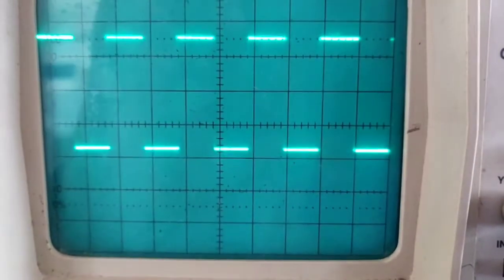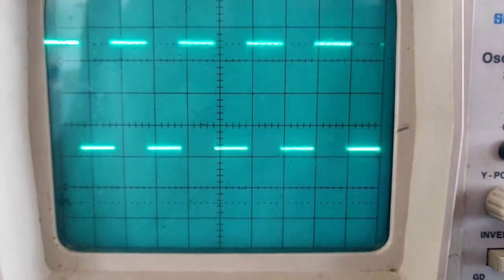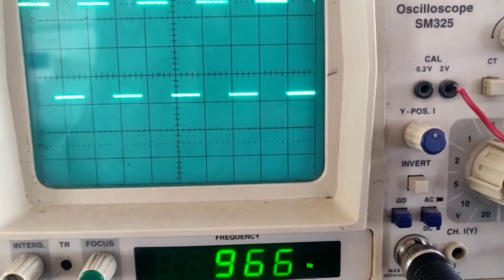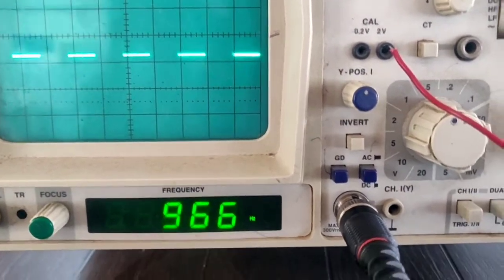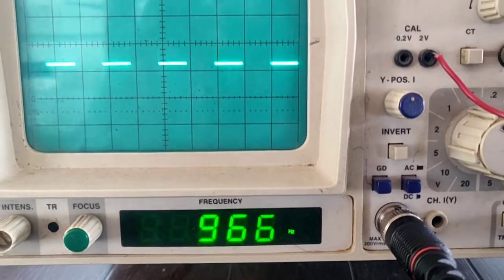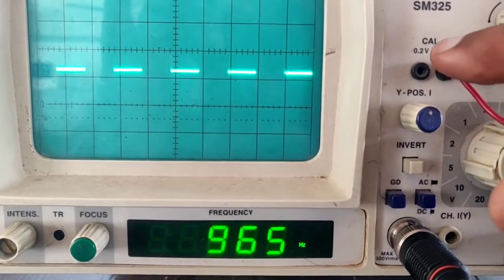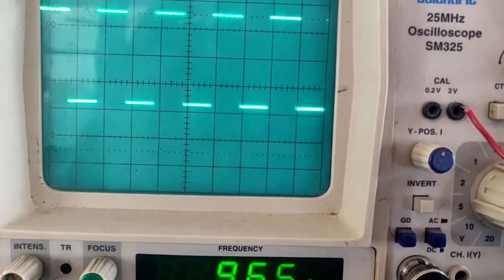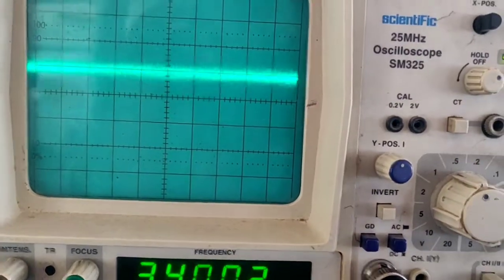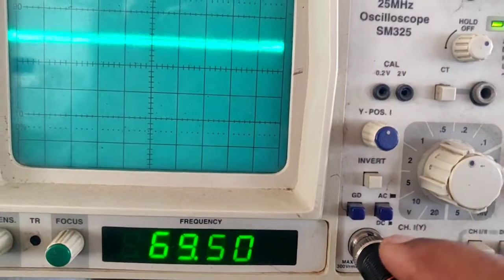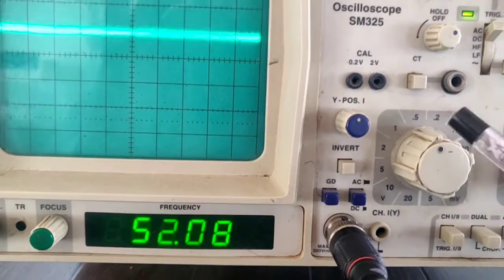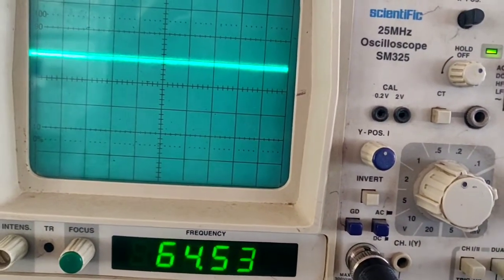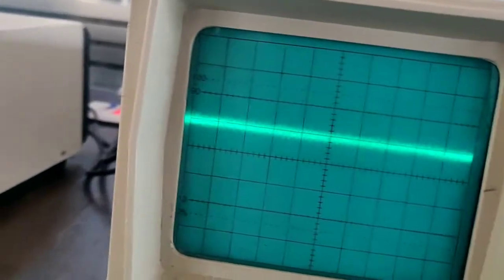But what happens, some students, I have observed that even though the CRO is working, they are doing a different method of operations. So in the initial stages, first you have to find out what you want to test, whether it is 0.2 volts or 2 volts, you decide. For that purpose, you have to select the first channel, because you have connected the CRO probe to the first channel, and you have to see the position of the volts per division control. Suppose if this position is somewhere here like this, you cannot see the square waveform here.